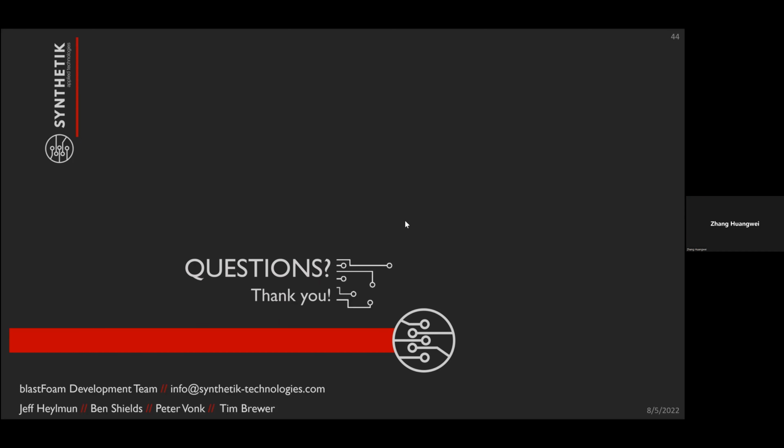Okay, thank you very much, Jeff. Yes, I think the volume fraction alpha is for the reduced five-equation model for compressible two-phase flows, so there's no Lagrange method here. Is that right? And how is this different from the VOF methods? The main difference from VOF is that we don't have a sharp interface.